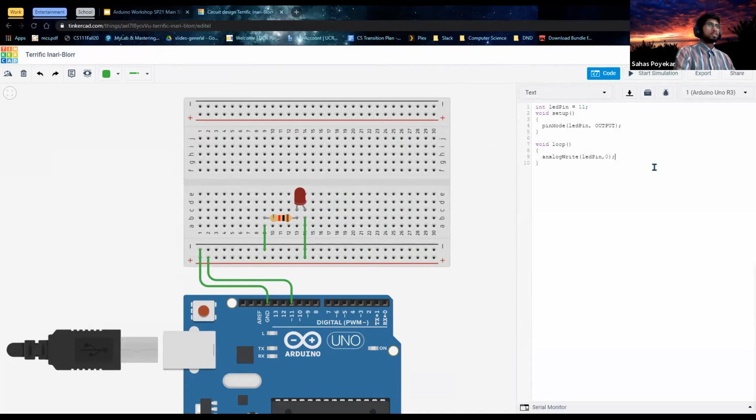In order to get it to actually distribute power, first we will use the delay function so that we don't automatically switch between 0 to, say, 500 really, really rapidly, so that we can actually monitor it cycling between everything. The delay function, any number you put inside of it, will be the number of milliseconds we will pause before we execute the next piece of code. Since I want to wait for 1 second, I'll put 1000 milliseconds in delay.